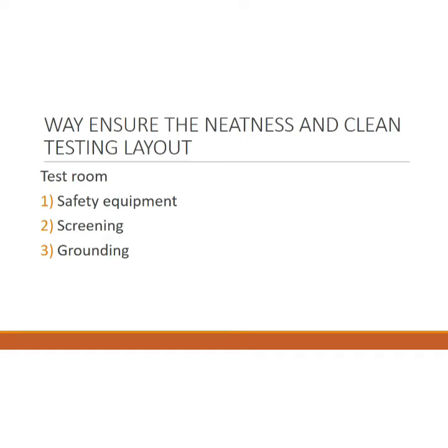Third is grounding. A good test field has to be separated in the grounding. This ensures there is no disturbance from the surrounding machines entering the test field, and in the case of failure, the earth potential of the surroundings does not rise, causing damage to the electrical equipment. It is necessary for the test field to have a lower grounding resistance than the surrounding building. That's all. Thank you.